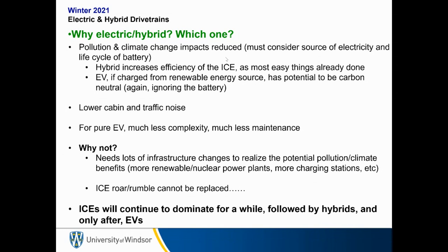There's not much more that can be done, because in the end, it's run on a cycle. And we all know you can't pass the Carnot efficiency of a cycle. So a hybrid would be a way to push an internal combustion engine beyond the Carnot efficiency, because we'd actually be recovering the energy during braking.